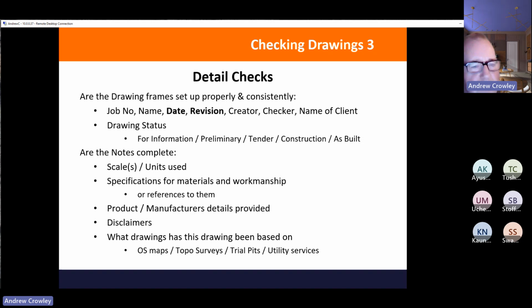And if you're using proprietary products, so there's all sorts of proprietary products like reid bars and so on, couplers and cast-in fixings and Hilti manufactured components, then put them on and refer to them by their reference number. It makes them much easier to buy and purchase as well. So say what the drawing has been based on.